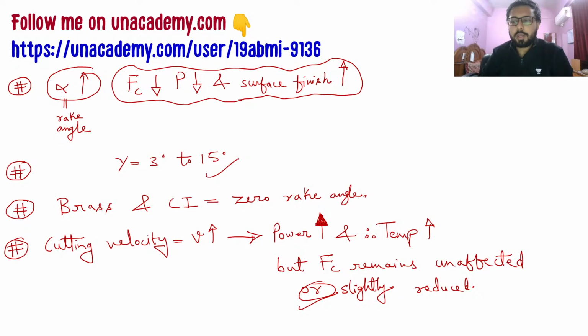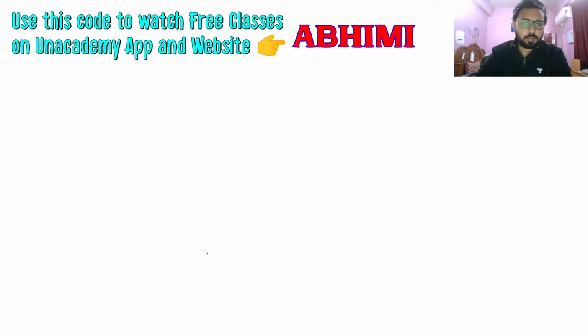More importantly, the thing that is going to be affected is cutting velocity. If it increases, then power will increase, and due to that temperature will increase, because power is force into velocity. So if velocity is increasing, your power will increase. So let's do the next thing here.